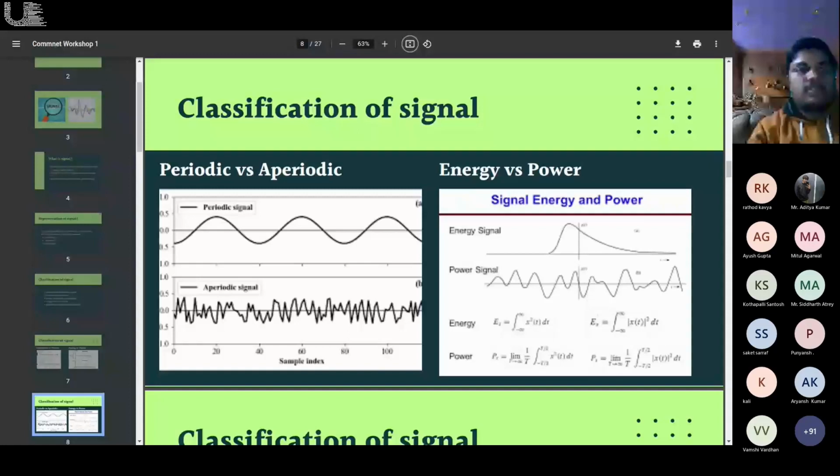So again, if we are considering the area between two zeros, meaning where the signal is touching zero, the time duration will be T by 2, right? If we find the area of the square of the sine signal from the first zero to the second zero, it will give the energy of the signal for that instant of time. And if we divide that energy by time T by 2, it will give us the power.